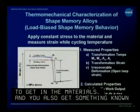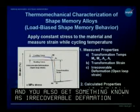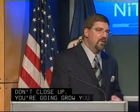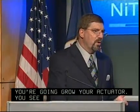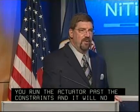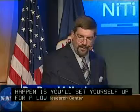Now that's a bad thing if the loops don't close up, because what will happen is with continued cycling, you're going to grow your actuator, and if you have very tight constraints, you're going to run the actuator past those constraints and it'll no longer work. Or worse yet, you're going to set yourself up for a low cycle fatigue condition, and the sample will fail relatively quickly.